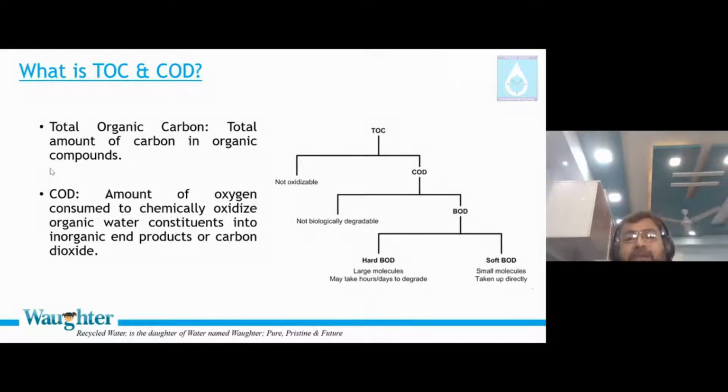Amongst the oxidizable portion, right? This diagram is presented just like this. I do not somehow like it. COD has got two classifications. One which will be reduced during bacterial action. That kind of thing we start wrongly referring to as BOD. And something which is not biodegradable, we just keep like that. A technical term for that is NBCOD.